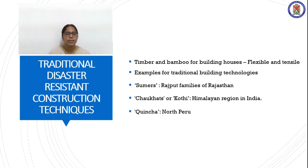So the earthquake resistant houses should have tie bands just above the level of the floor, at the level of the doors and also the windows, and another at the roof level. And corners are the most vulnerable and should be strengthened. The elasticity of the structure can be enhanced with flexible steel rods or wood materials at corners.